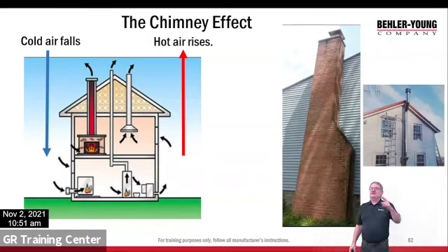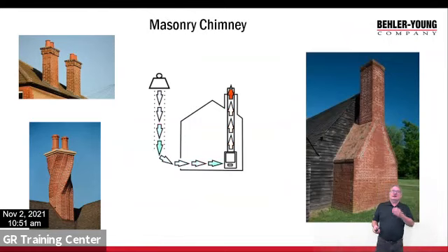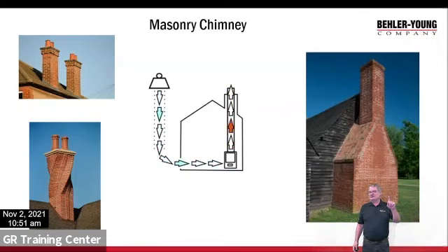All right. If you look at this one here over my shoulder, you can see this is a Class A chimney. This would be a wood stove, but you see it's extending beyond the peak of the house. All right, that's the key. It's got to be higher than anything else around it for this all to work. All right, but it is a pretty ingenious device. All right, so we look at all these different chimneys. They're doing the exact same thing. They're the highest thing around.